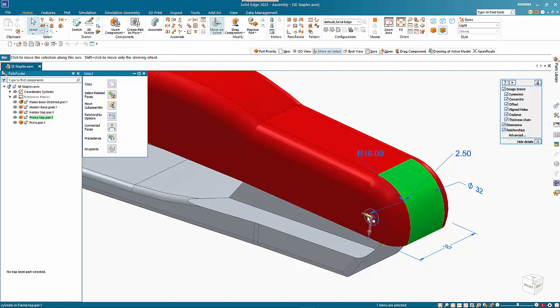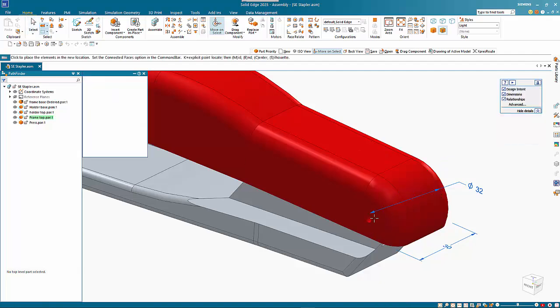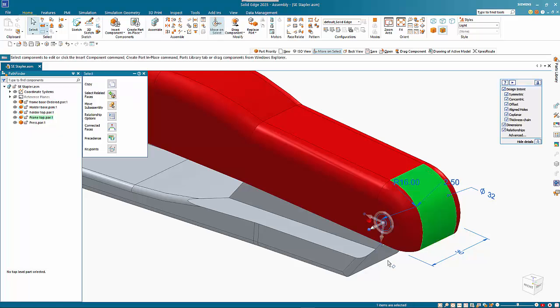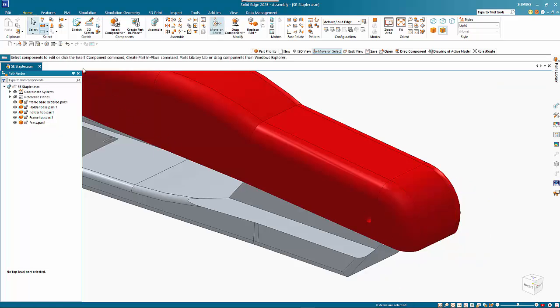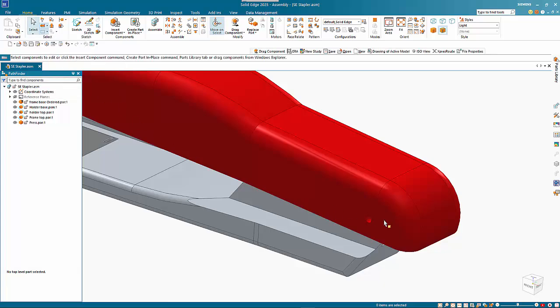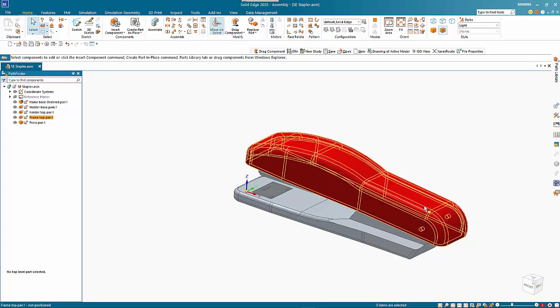So going to my steering wheel, I can then just drag this out, and I'll bring it out, say about 5mm. So I can type that size in and just drag that so that we have options for a little bit more movement. So obviously you can switch between the two here. You can see on the prompt, Control Spacebar will put me back to priority in selecting parts.